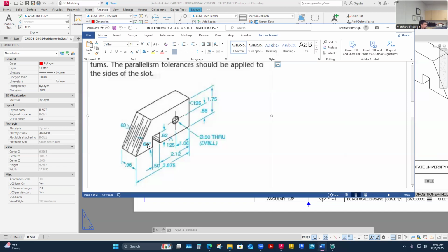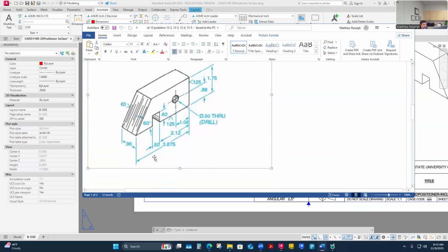It's not something we've used on any of our drawings yet, but I think there's 3 different types that show up on these ADA quizzes. Parentheses ones are reference dimensions, meaning they're not the critical controlled ones. They're nice to know, but don't control the part. Basic dimensions are more GD&T based, with a box around it. And an underlined dimension is not to scale. I'll look that up before we leave.